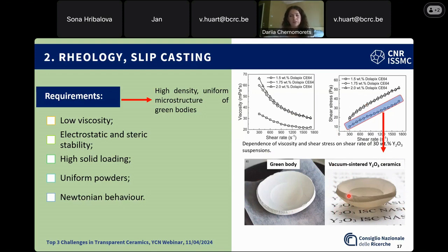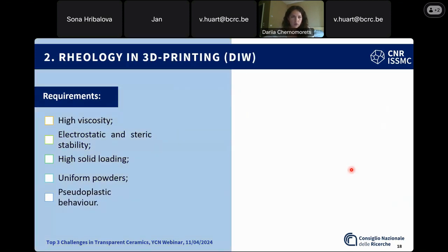So in the case of HIP, that's usually not a big issue, at least from what I have experienced and seen. Of course, what you can and might want to do is not to place the samples for hipping in crucibles, but to place them in a powder bed, if you really don't trust the crucible.